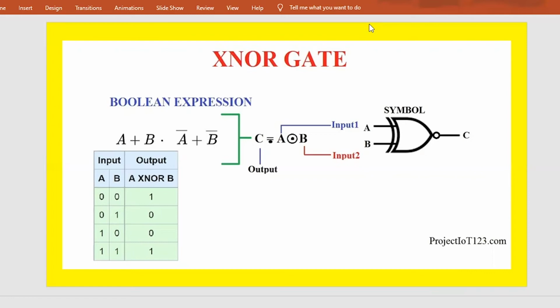If a specific type of gate isn't available, a circuit that implements the same function can be constructed from other available gates. A circuit implementing an XNOR function can be trivially constructed from an XOR gate followed by a NOT gate. An XNOR gate circuit can be made from 4 NOR gates.